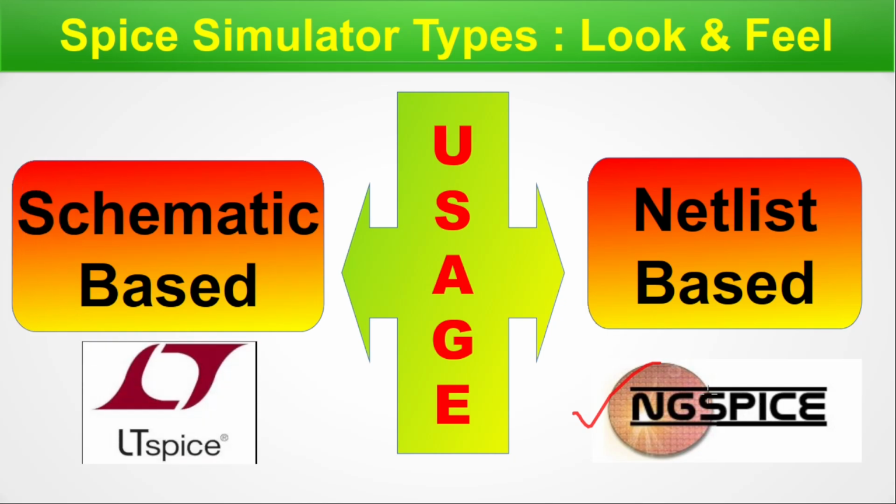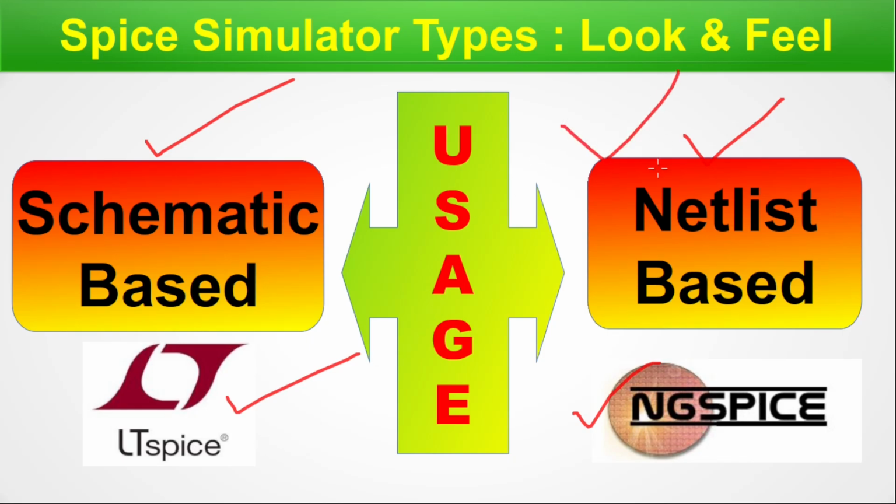The next category is the schematic based, and here the candidate is LTSPICE, which is a free tool. We are not covering the LTSPICE in this series. We are covering rather the netlist based SPICE tool in this series because that is the very fundamental thing. Even if you are using a schematic based SPICE tool, under the hood, it actually is simulating a netlist that is generated by this particular schematic tool. The schematic tool at the bottom even uses a binary to simulate the SPICE deck that it builds from the schematic.